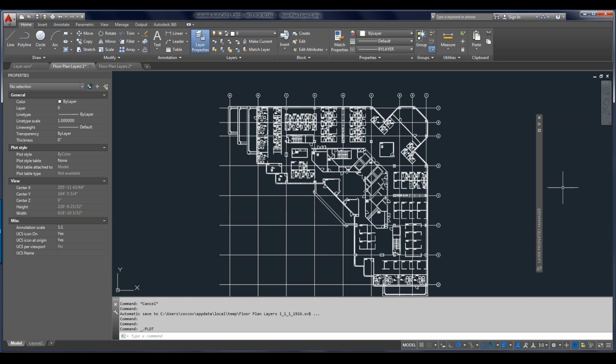with that checkbox on, a lot of it depends on the settings of your actual plot device. So when you go into the plot window, you may want to go into the settings of your plot device as well, and there's sometimes settings in there depending on what your output is. But a good rule of thumb I've found is to just check that plot transparency that Volker showed, and then go ahead and send a plot.